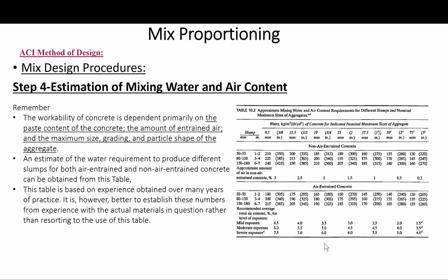It is, however, better to establish these numbers from experience with the actual materials in question, rather than resorting to the use of this table. As we said before, if you have accumulated enough information and data about the material in question, you could develop your own tables and curves rather than just using the standard curve in ACI. So when water reducing admixtures are used, these values from this table should be decreased according to the amount of water reduction anticipated. All right.